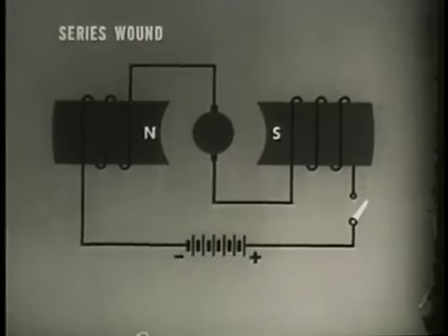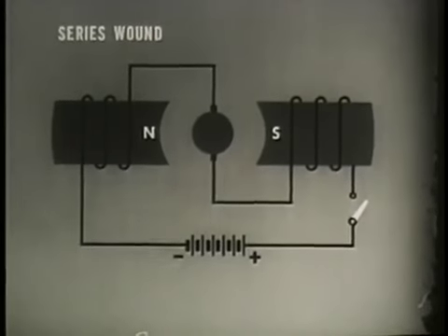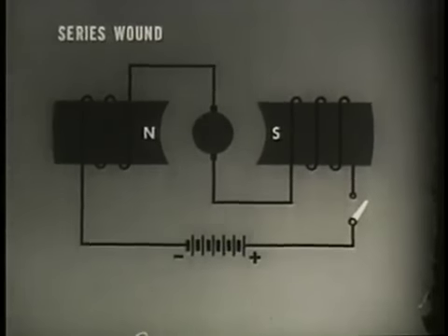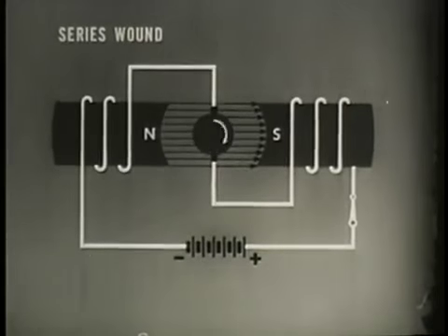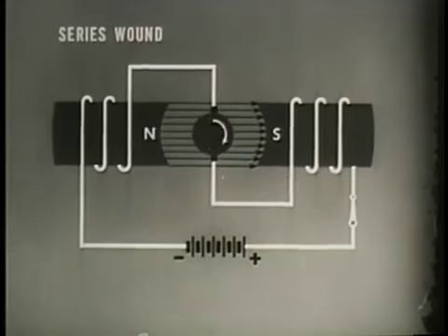The series wound motor has good starting torque, or turning force. Torque depends on armature current and on field strength. Since field strength is proportional to current, the high starting current before CEMF is developed affects torque as the square of the current. The motor begins to turn, attempting to develop enough CEMF to completely oppose the applied EMF.